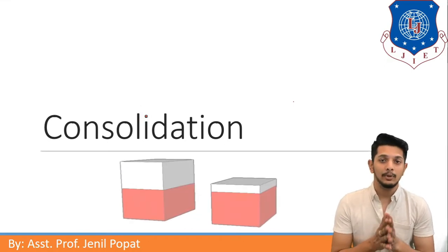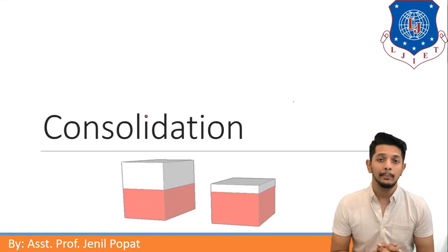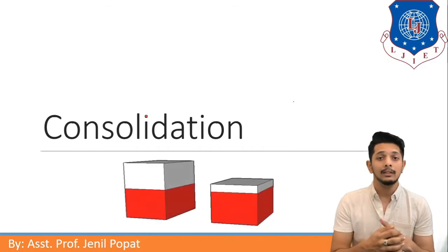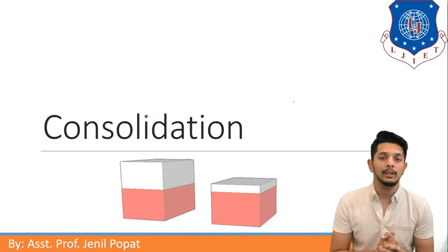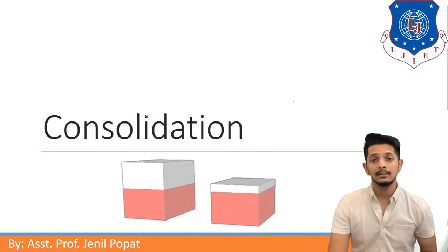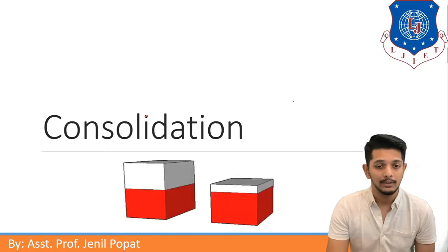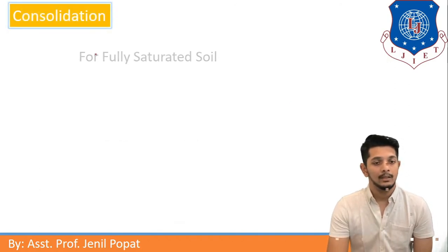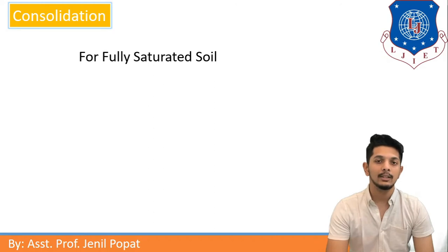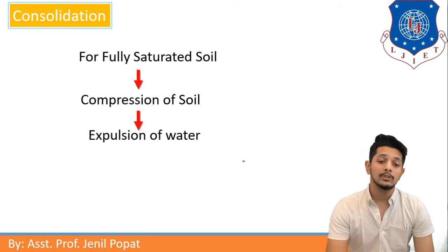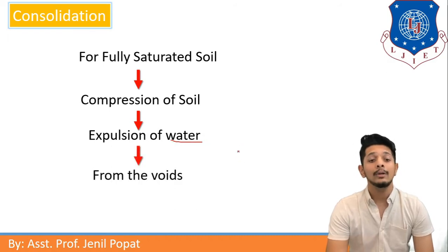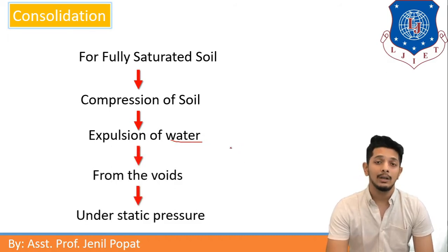Consolidation is a natural process. Consolidation happens over time, by natural loading, or we can say static loading. Let us discuss technical sides of consolidation. For fully saturated soils, compression of soil happens due to expulsion of water from voids under static pressure. It is called consolidation.